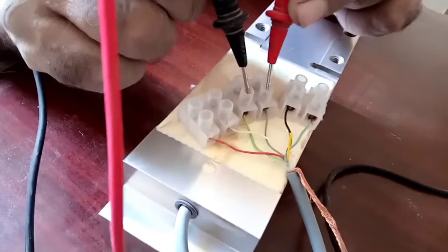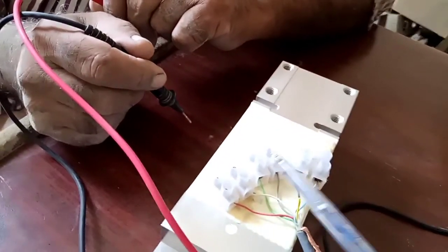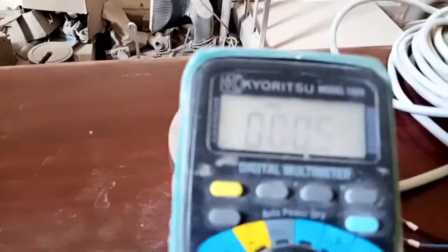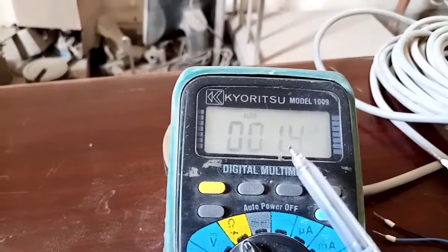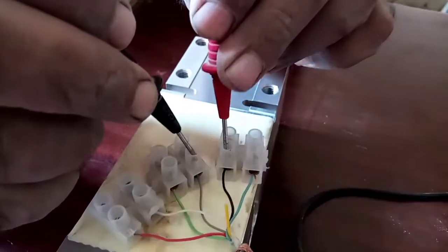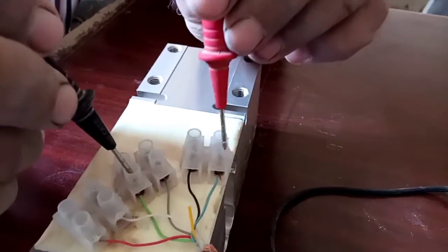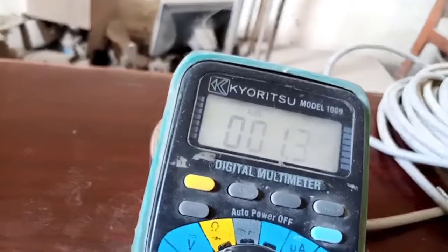And also we can check one wire shorted with the other input and excitation wires. Now I check black and gray wires, one input wire and one excitation wire, and its resistance is almost 0 ohm or 1 ohm, it's 1.1 ohm, not a kilo ohm, just an ohm. This is the wire resistance, and also green and blue are the same values, excitation and input wires, 1.4.